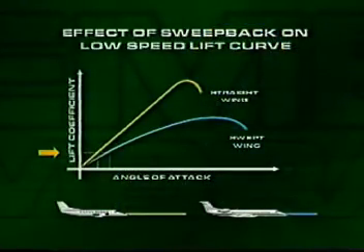We have just demonstrated that in the swept wing, the speed component of the wing responsible for lift is lower than the real airspeed flown by the whole aircraft. Thus, lift is correspondingly reduced. There is no doubt wing sweep removes some basic lift. Check in the figure that idea. Observe that for the same angle of attack, the unswept wing produces more lift than a corresponding swept wing.